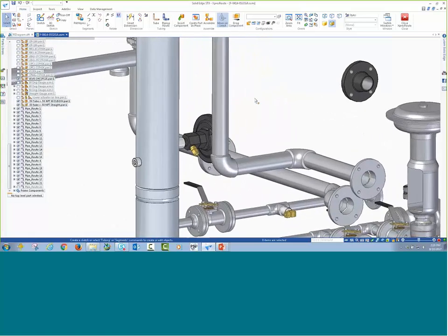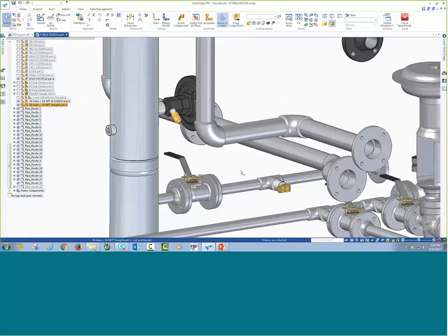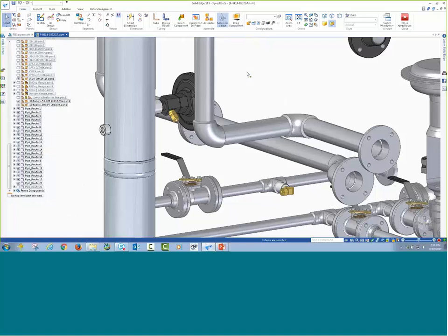As I zoom in here, again, we have some brass fittings, and I want to go through and create a route where maybe a tube might reside. We talked about creating those routes manually earlier. We also have this handy tool called Path Express. Path Express allows us to simply select the starting and ending points.